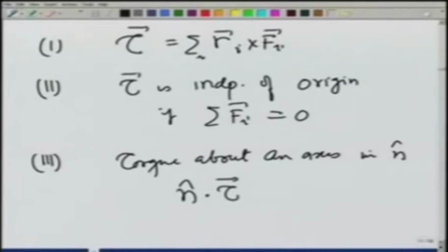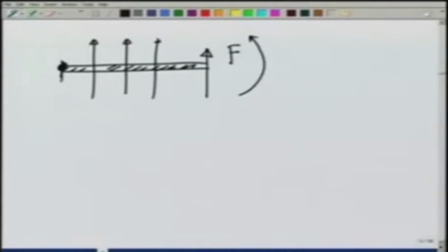Next, what we will do is, using the couple moment and force, we will like to transfer a force parallel to itself and see the effect of a force, how it is seen at some other point. For that, let me just motivate you by taking a rod and apply a force here. If this rod is fixed here, what you will see is that this force will, number one, push the rod in this direction and will also tend to rotate it like this.